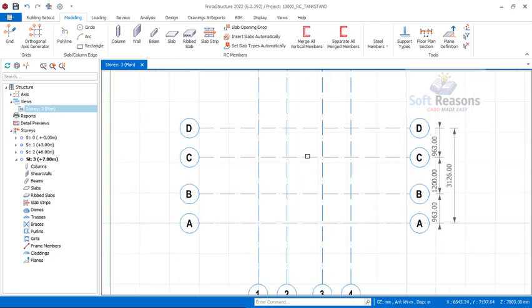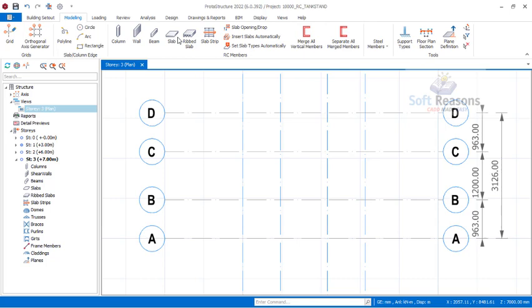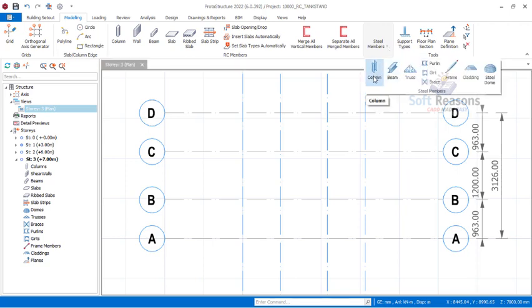All right, so here we are, this plan view. You just have to, because it's going to be a steel. Okay, so we will navigate to where we have modeling right there. Go to steel. Okay, steel members, and then we'll be considering this the steel columns.